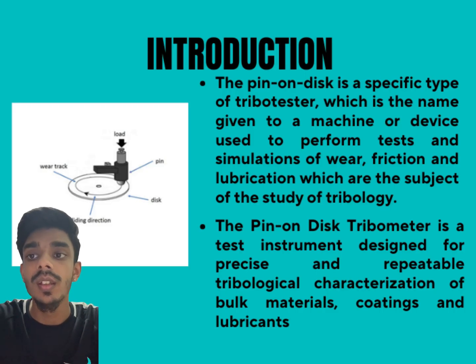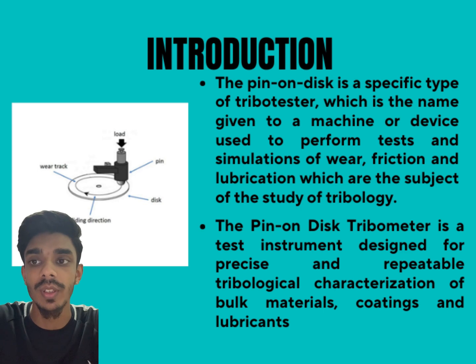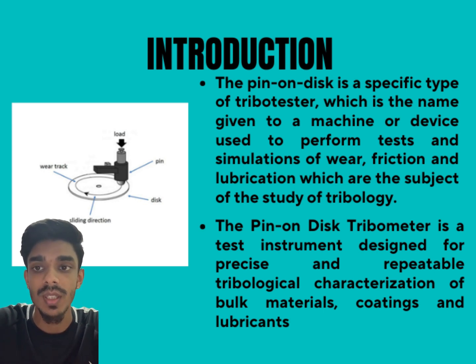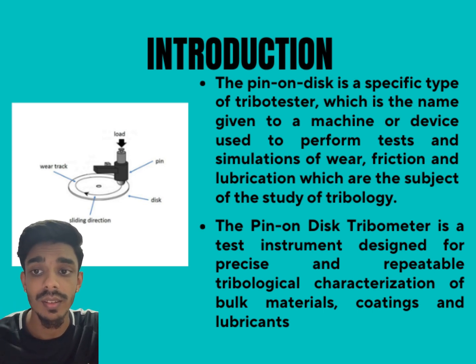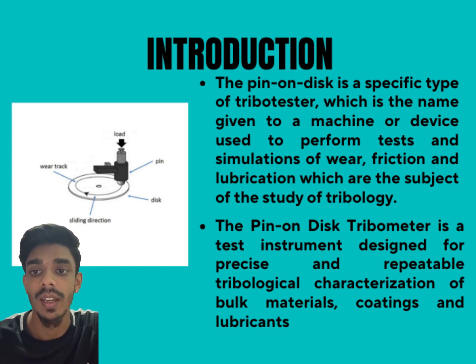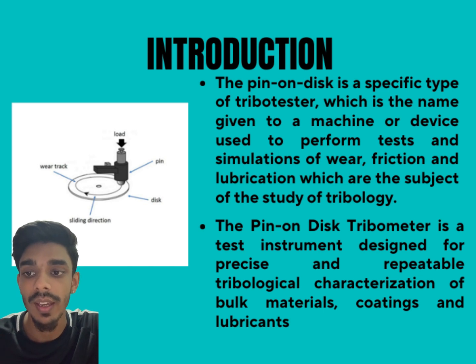Okay, for the introduction of this lab, the pin on disc is a specific type of tribometer, which is the name given to a machine or device used to perform test and simulation of wear, friction and lubrication, which are the subject of study of tribology. The pin on disc tribometer is a test instrument designed for precise and repeatable tribological characterization of bulk materials, coatings, and lubricants.